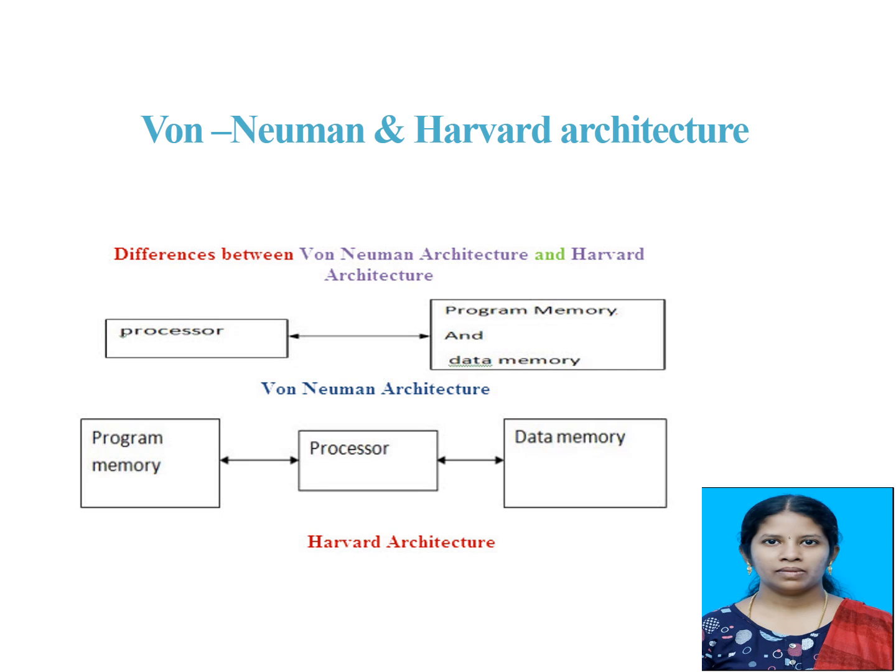Since the data and the instructions reside in the same memory, there is erasing of data by one another, thereby producing system faults. To overcome this drawback, Harvard architecture was introduced. Harvard architecture is the digital computer architecture whose design is based on the concept where there are separate storage and separate buses for instruction and data.